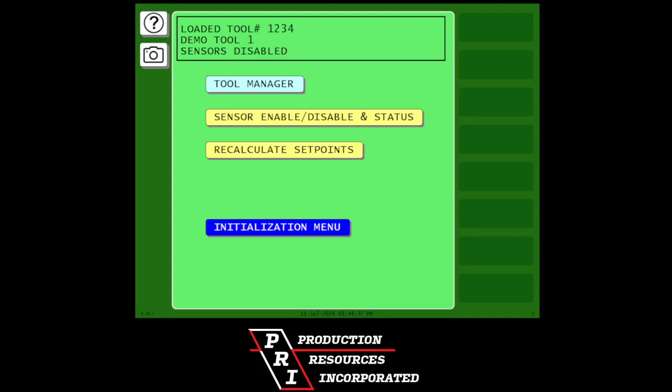In this video, we will be programming a green quick check sensor. Green quick check sensor is an event type known as a cyclic event. Cyclic events occur once a stroke at a predictable degree angle. This is called the ready signal. The ready signal is when we will look for the green quick check sensor activation to occur.